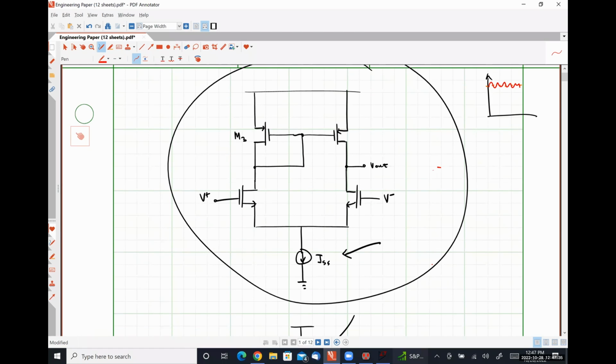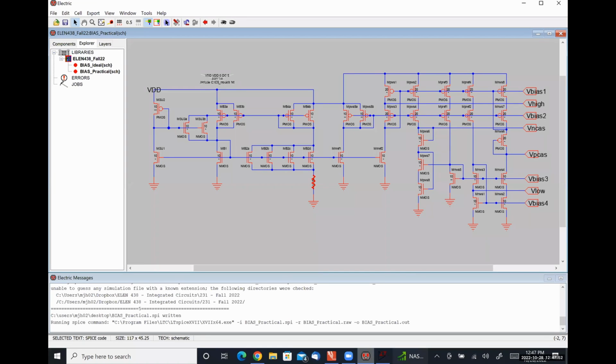If we went NMOS into NMOS, we're going to have a very, very small amount of headroom to use. So we have to make sure that we're going NMOS into PMOS or PMOS into NMOS before we hit our output stage. Anyway, that's enough ranting about where we're going. Happy to answer and entertain any questions you may have, but I've already built it, and the schematic representation of doing it is much less of a pain in the butt than the layout version. I'm going to work on the layout version.